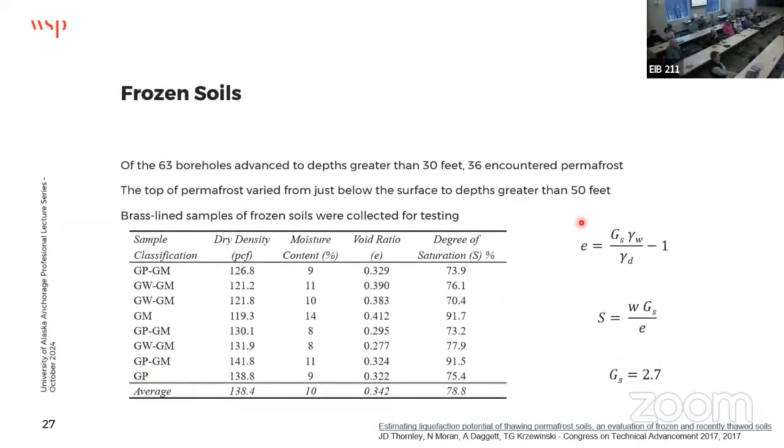So for the current void state, I assume a specific gravity or measure a specific gravity. I've got my unit weight of the water and I've got my unit weight of soil. So the easy one is to actually measure the in situ or the current void ratio. The harder one is to measure e min and e max. You typically need to have a larger sample and then run a number of tests to understand where the e min and e max are. But understanding where you are, at least, within that continuum is a lot easier. So it's one you can directly measure.